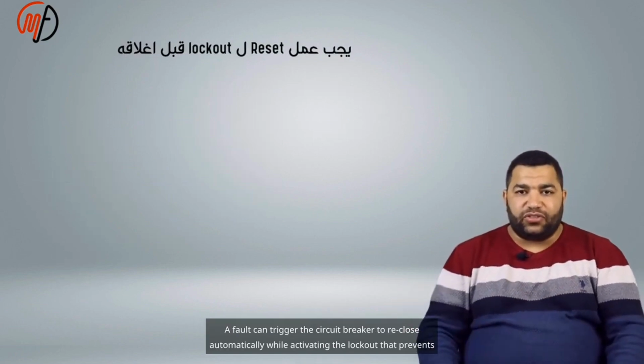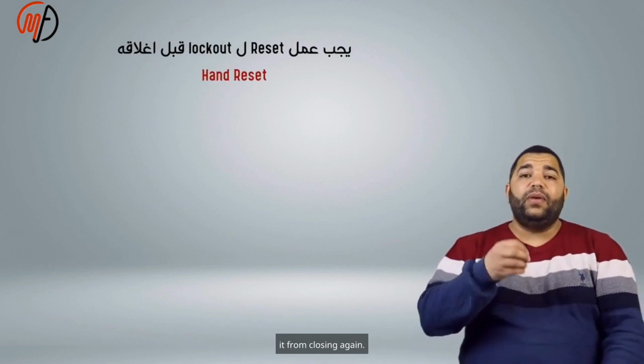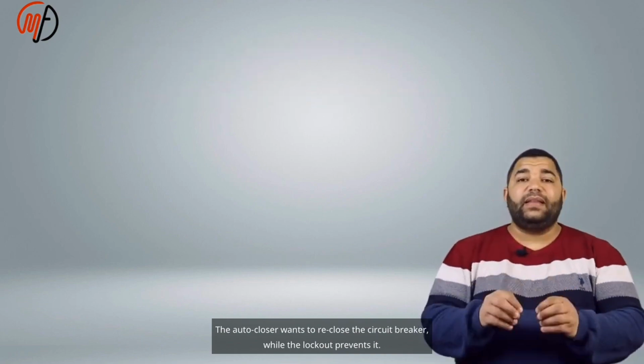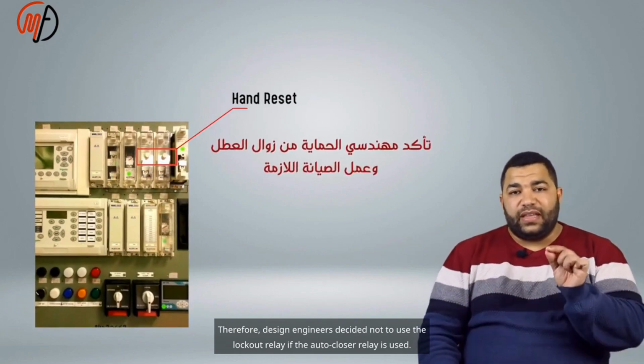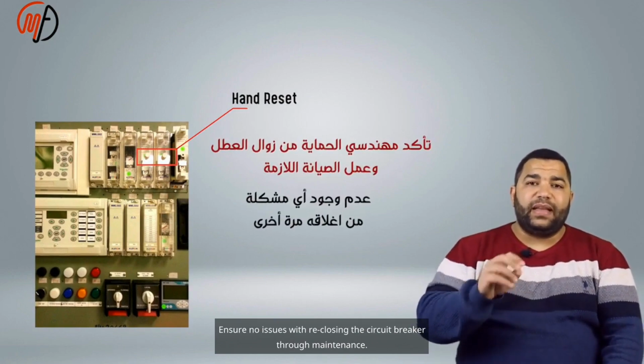A fault can trigger the circuit breaker to reclose automatically while activating the lockout that prevents it from closing again. The autocloser wants to reclose the circuit breaker while the lockout prevents it. Therefore, design engineers decided not to use the lockout relay if the autocloser relay is used. Ensure no issues with reclosing the circuit breaker through maintenance.